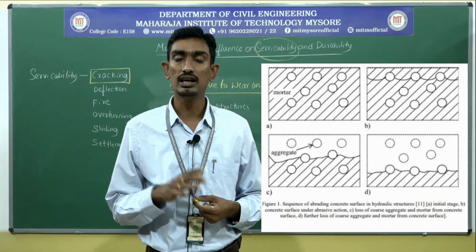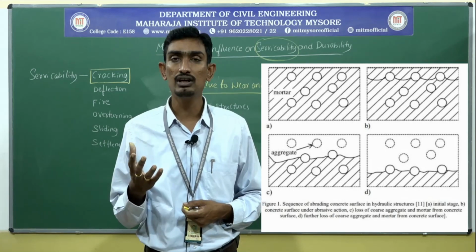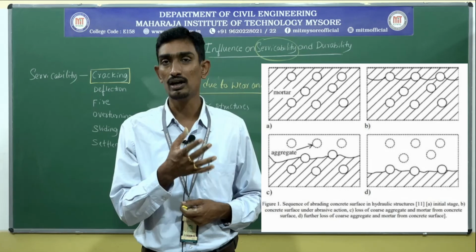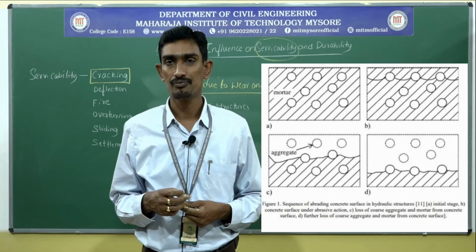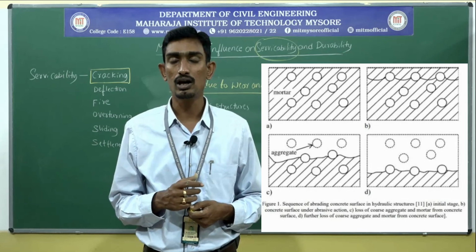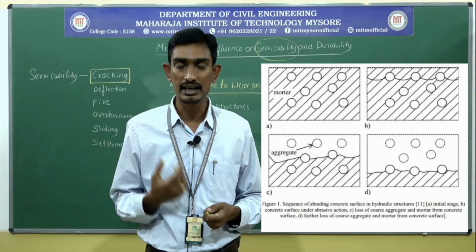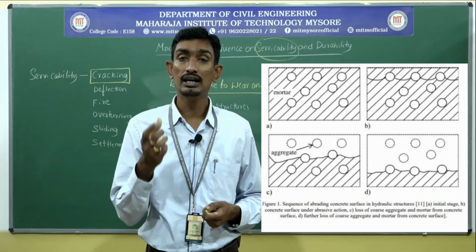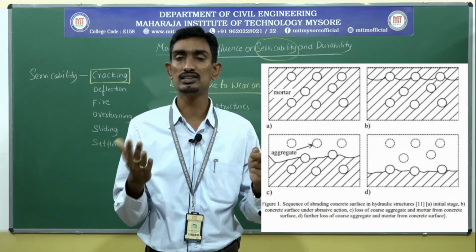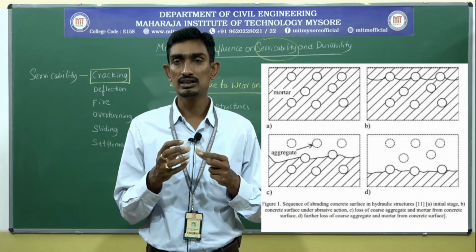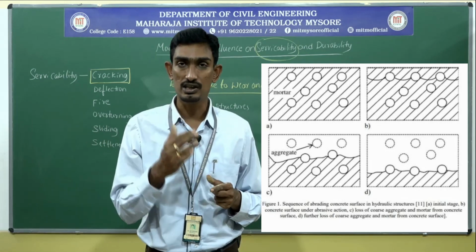Because of this riprap movement or debris inside the concrete structures, the water movement will try to remove those aggregates, or the cement paste, and create imbalance. This removal of aggregates leads to a reduction in paste bond strength. Because the bond strength between the aggregates and the cement paste is reduced, obviously the aggregates will be detached outside, and the cement paste will be loosened with deficiencies.